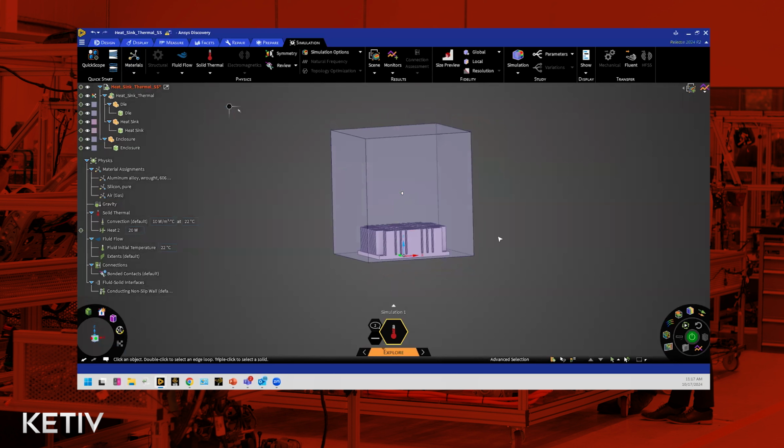So we've assigned a heat source, we've built an enclosure, we've automatically gone through the physics list and turned on gravity. The other thing is to define the boundary conditions at the extent of the domain. So typically in forced convection flows, even if you have an inlet with a velocity assignment, you're providing a certain velocity, and depending on the magnitude of the velocity, it could again be a forced convection problem, right?